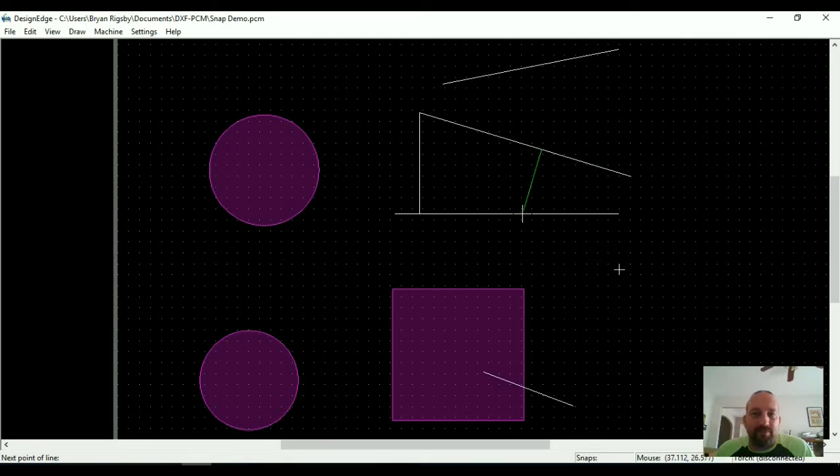I just write in here. So I click that. Now I've got an intersection. It actually does run down and connect because I said H on that path, and it's perpendicular to this line here. So that's a 90-degree angle down to this because we said perpendicular, and that's the first one we clicked.